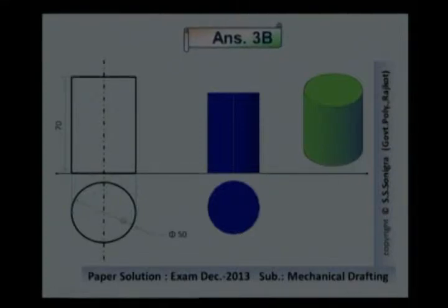It's needed, because the cylinder does not have any outer surface or outer edge. It's needed to divide it into an equal number of parts. Suppose here it is divided into 8 parts at an angle of 45 degrees. Name each point on the periphery of the cylinder, that is A, B, C, D, E, F, G, H.